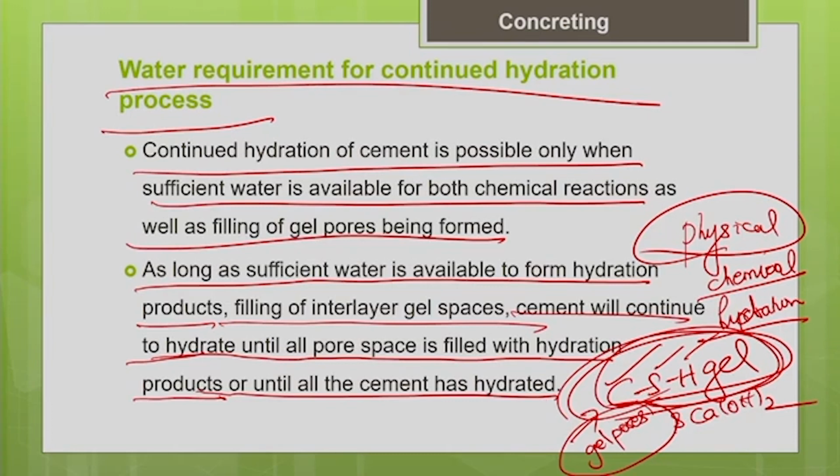So, this hydration process will keep continuing till the water is available to form these hydration products and to fill the gel pores, till all the pores are filled.